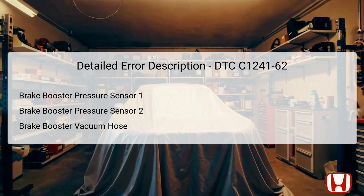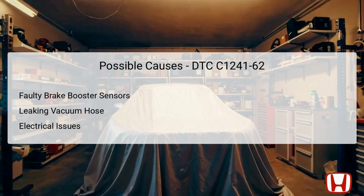If the sensors detect larger discrepancies than specified, the control unit will conclude a fault and set the C1241-62 code. The brake booster vacuum hose connects these sensors and ensures that they are functioning correctly. Identifying the correct location and operational context of these components is key to effective diagnosis. The first probable cause of DTC C1241-62 is faulty brake booster pressure sensors.